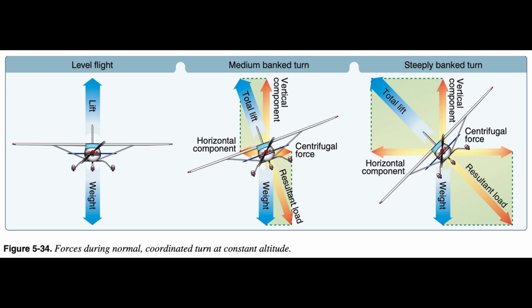If an aircraft were viewed in straight and level flight from the front, Figure 5.34, and if the forces acting on the aircraft could be seen, lift and weight would be apparent, two forces. If the aircraft were in a bank, it would be apparent that lift did not act directly opposite to the weight, rather it now acts in the direction of the bank. A basic truth about turns is that when the aircraft banks, lift acts inward toward the center of the turn, perpendicular to the lateral axis as well as upward.